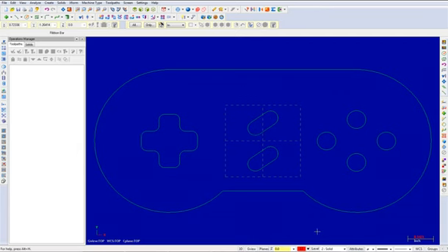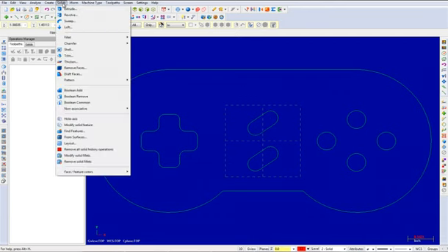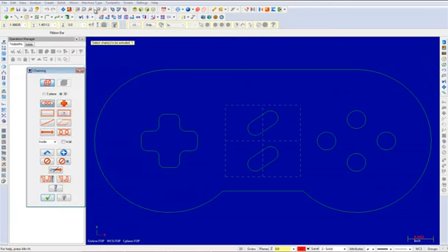We will now extrude the base of the solid. Extrude function lets you extrude geometry to create one or more solid bodies, cuts on an existing body, or create bosses on an existing body. That being said, select Solids, Extrude. When the chaining dialog box appears, leave the default settings. From the graphics view, select Isometric.